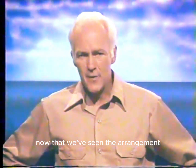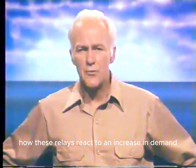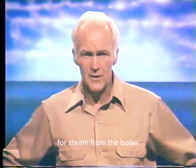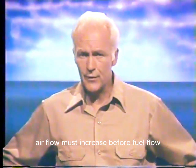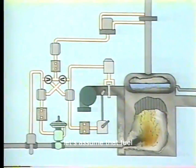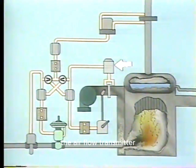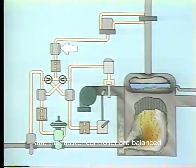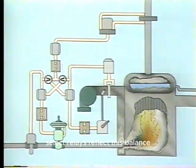Now that we've seen the arrangement and type of relays for this system, let's see how these relays react to an increase in demand for steam from the boiler. Remember, when demand increases, airflow must increase before fuel flow. Let's assume that fuel and air are being supplied to the furnace in the proper mixture and that the system's in balance. When the system's in balance, the output signals from the fuel flow transmitter, the airflow transmitter, and the master controller are balanced, and the output signals from the high and low select relays reflect this balance.